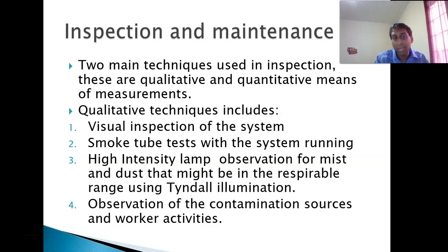If the LEV system was meant to extract dust, but on your work surfaces, on the benches, on the desk, on the clothes of workers, or on products you have there, it feels dusty, then it means that something is a bit wrong, right? The LEV system is not doing what it was supposed to do anyway, right? You could also probably look at the health of the workers. If a worker was coughing, complaining, right, of the area feels dusty and his eyes would have been irritated, all of those would have been qualitative means of assessing the effectiveness of the LEV system, right?